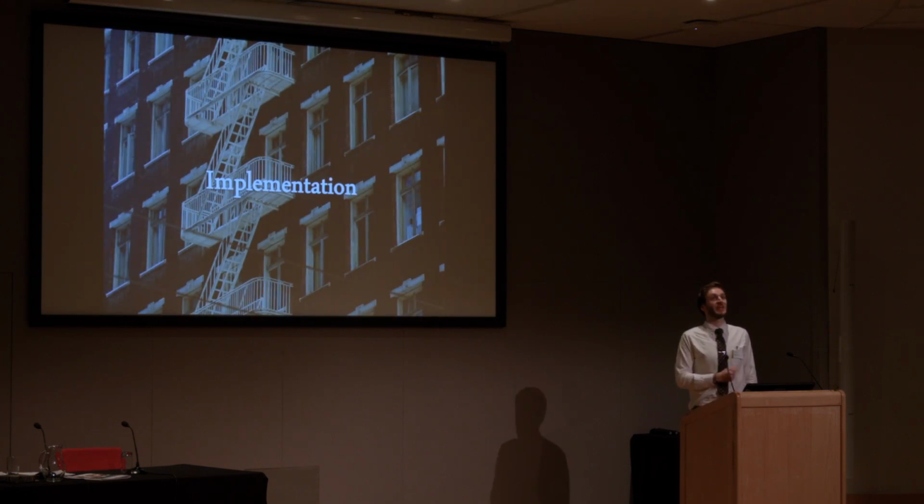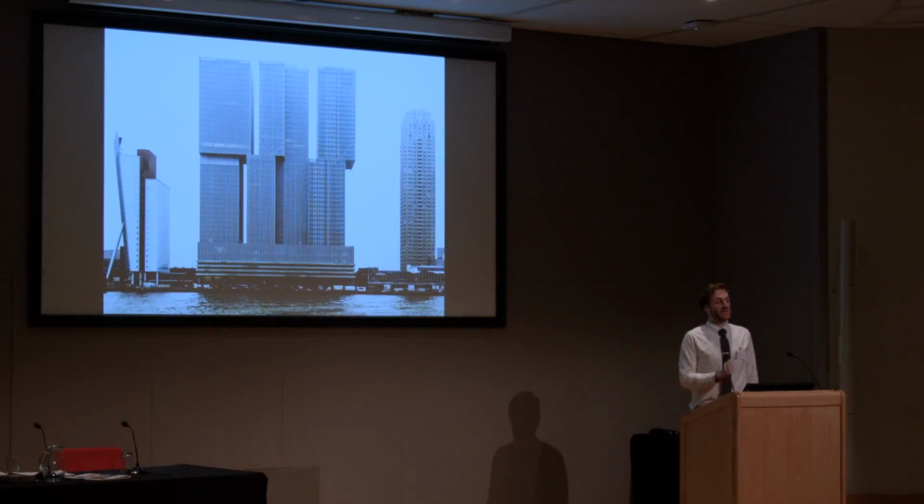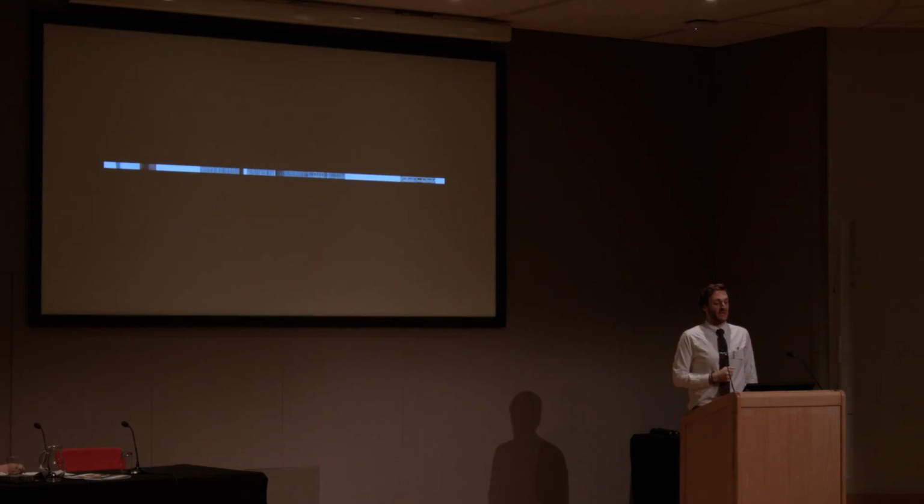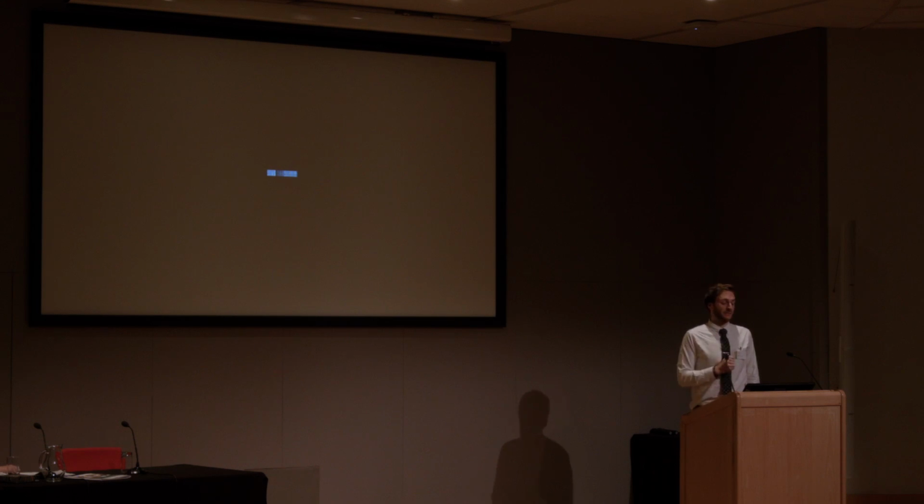So the implementation of the hybrid model, once I've finished the validation, actually from an impact point of view, my hybrid model is now part of the Fire Dynamics Simulator software, which is the most used CFD tool in the industry. It might look something like this. We go back to our building, and it's the same fire safety issue that we want to look at, same location. Again, we'll curtail 31 and above, 29 and below, and we'll curtail down to our room of fire origin and a handful of enclosures.